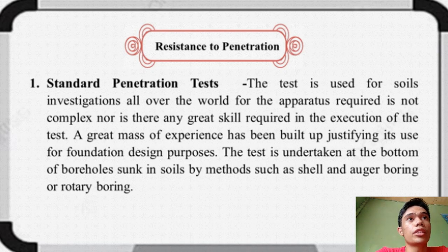The standard penetration test. The test is used for soils investigation all over the world. The apparatus required is not complex, nor is any great skill required in the execution of the test. A great mass of experience has been built up justifying its use for foundation design purposes. The test is undertaken at the bottom of a borehole, sunk in soils by methods such as shell and auger boring or rotary boring.